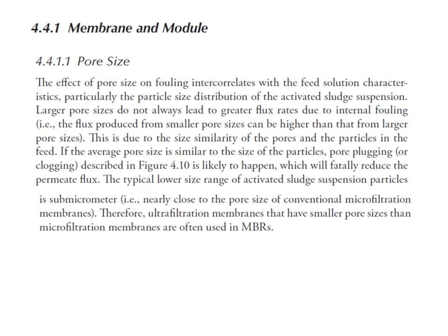Okay, let's look at them one by one. When we consider membrane and module, pore size is the first factor that we have to consider. The effect of pore size on fouling intercorrelates with the feed solution properties, particularly the particle size distribution of the activated sludge suspension.